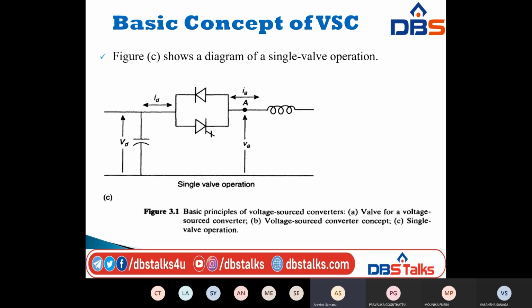You already know that. Here the DC voltage, that is VD, on the left hand side is assumed to be constant. In the previous case also we assumed the DC voltage constant, and supported by a large capacitor. In the previous case also the DC voltage is supported by a large capacitor. That too with the positive polarity side connected to the anode side of the turn-off device.